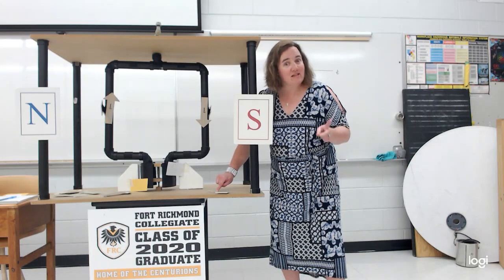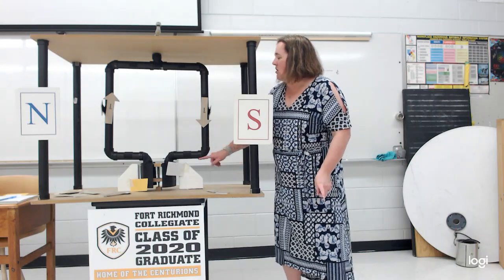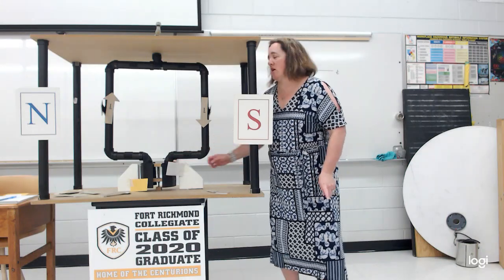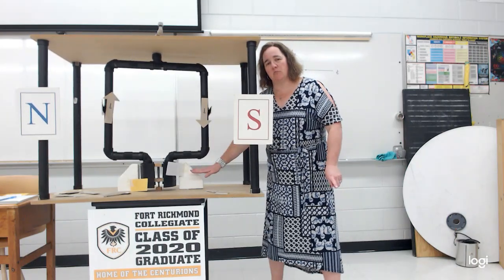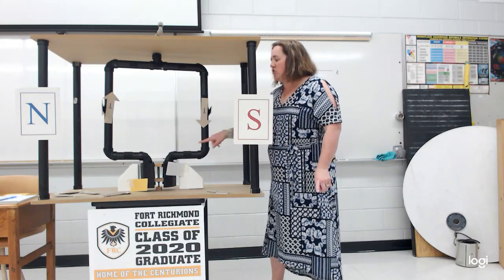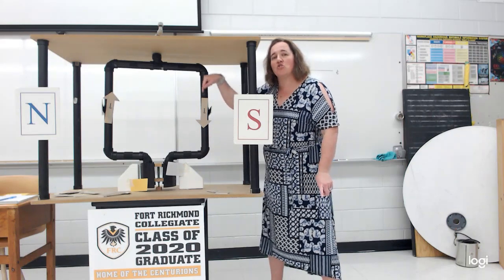Wait a second, that's what's different. So now this side of the commutator, which was on that side before, is now touching this brush. And this brush is receiving this direction of current.